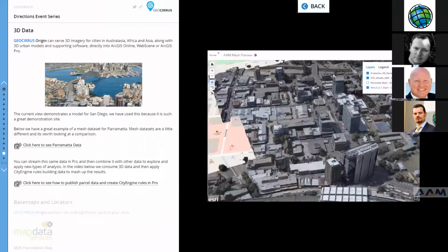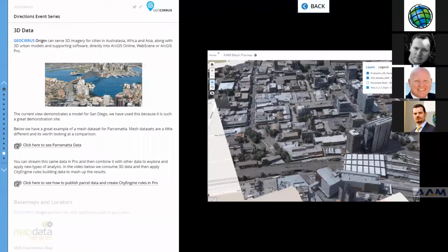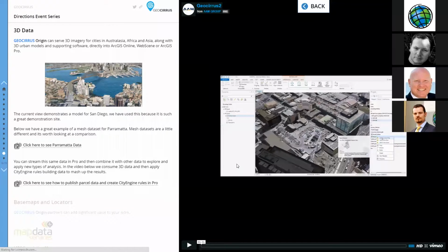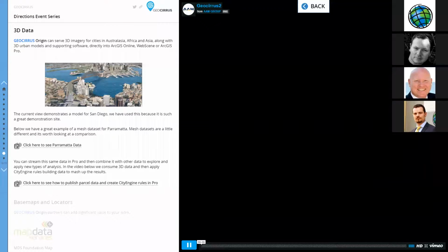I'm going to move on again and actually show you how we can use this data in Esri applications. Okay, so I'm going to play a video. And this video is going to show a couple of things. We're going to start off within Pro, and we're going to add our 3D information. We're then going to add some 2D information. So we've added 3D, we're going to add 2D. And then we're going to apply a CityEngine rule to that 2D information to extrude it to represent new planning rules within the area. So here we go.